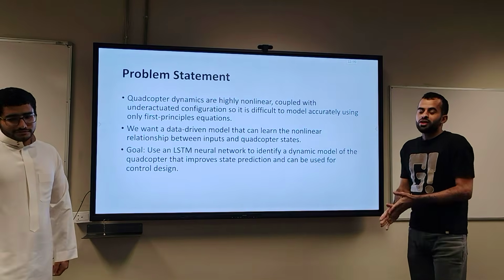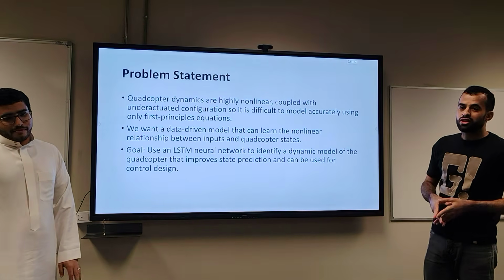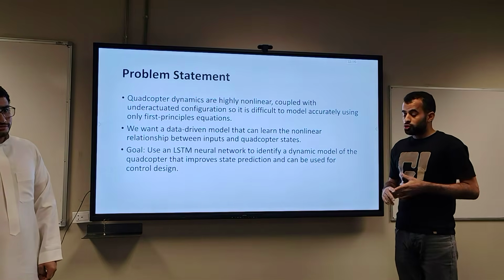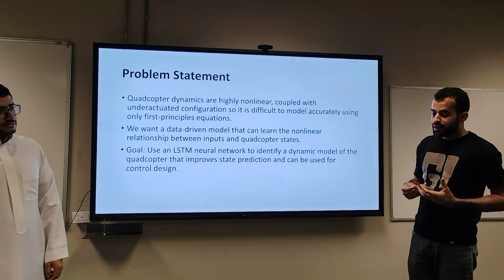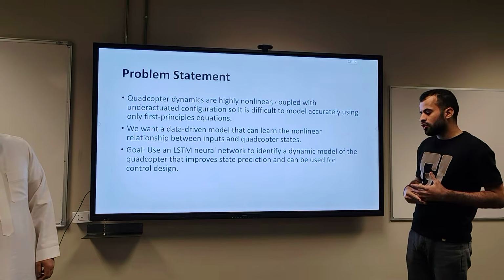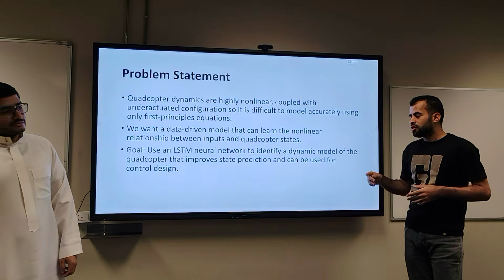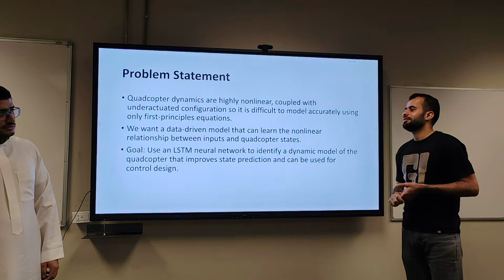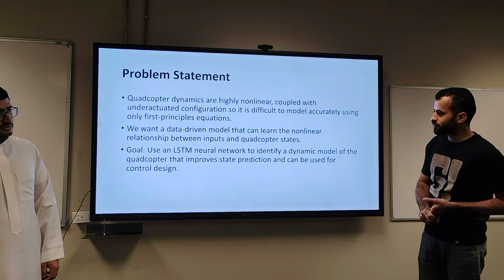Problem statement: we know that the quadcopter is highly nonlinear, with a coupled and under-actuated configuration. To design an effective controller, we need an accurate model. We cannot achieve an accurate model using only physics, so we go one step further through system identification.